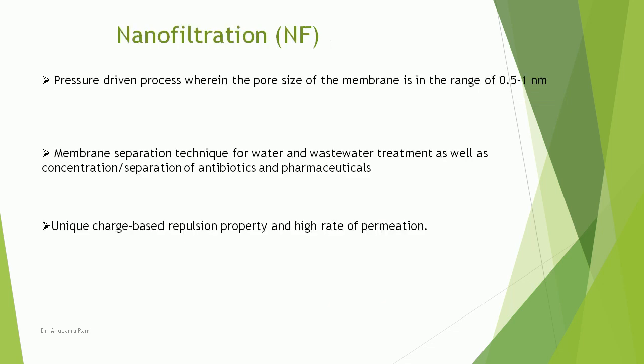Nanofiltration (NF) is a pressure-driven process wherein the pore size of the membrane is in the range of 0.5 to 1 nm. It is a membrane separation technique for water and wastewater treatment, as well as concentration/separation of antibiotics and pharmaceuticals. It has a unique charge-based repulsion property and high rate of permeation.